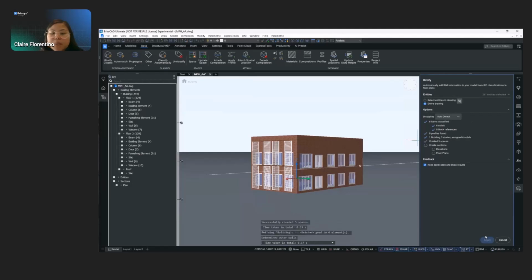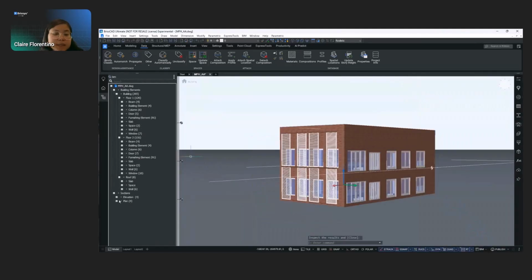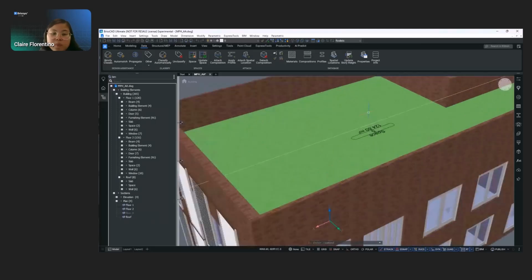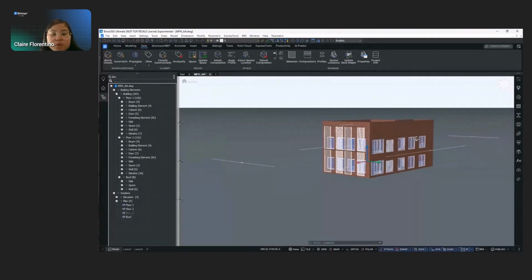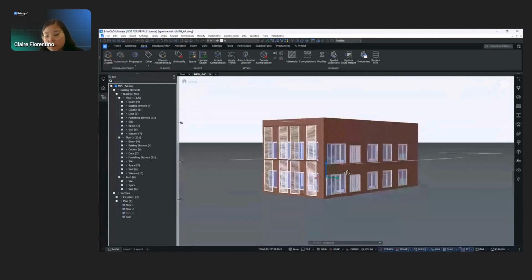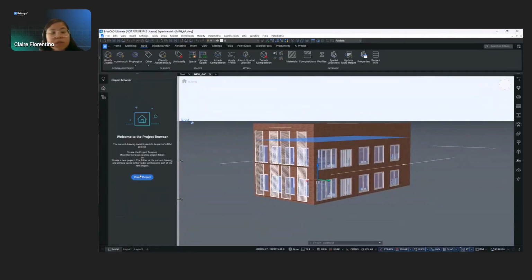The documentation is based off of the plan sections or the elevations. So I use BIMify. Just with the word alone, it basically BIMifies your model, adds more BIM information, creates spatial locations, creates those floor plan sections for you. In this case, we now have a floor 1, floor 2, and a roof as our floor sections.